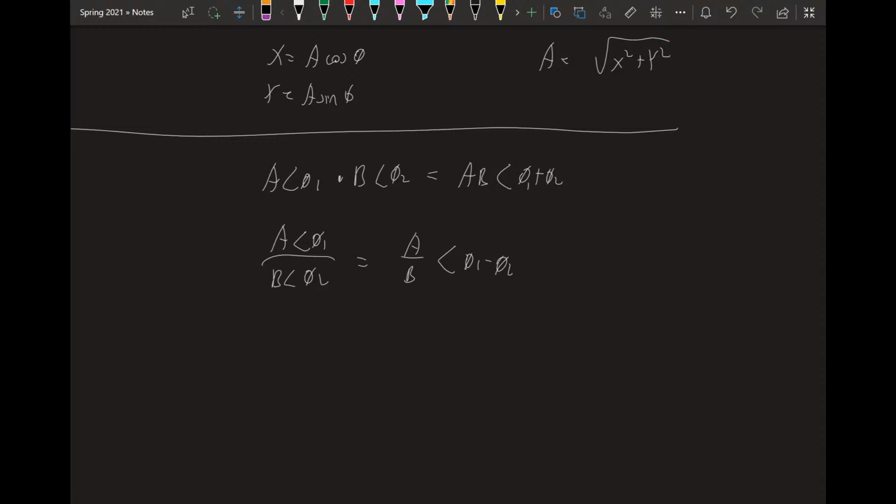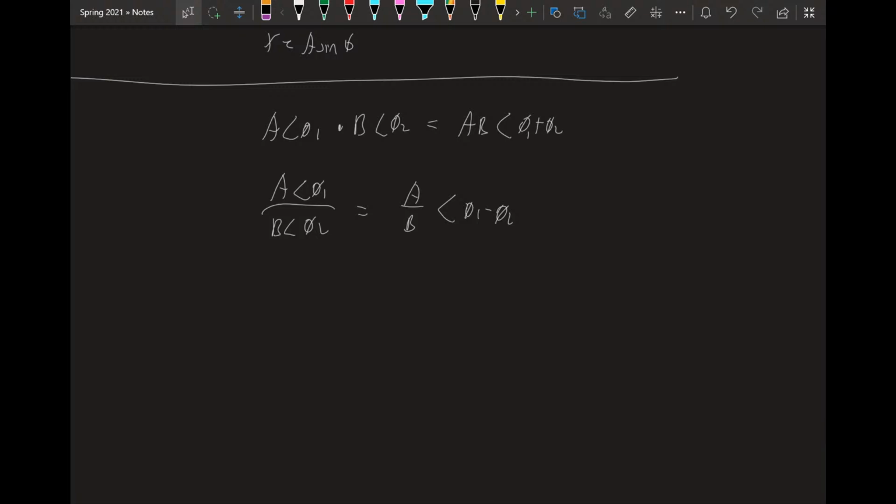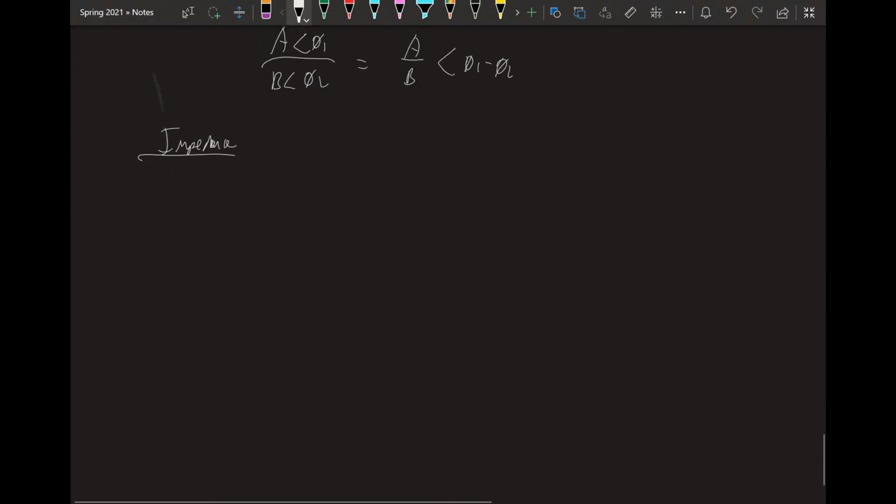But why is everything complex? That's weird. Well, no. Before we didn't have to deal with complex resistances or impedances, but now we do because there's an AC signal. So each of the three components we know, resistor, capacitor, inductor, has what's called an impedance. Impedance is how a component impedes current flow, just like resistance, but now it's AC current flow. So a resistor has an impedance represented with Z, and its impedance is just a resistance. It's a linear element, doesn't matter.